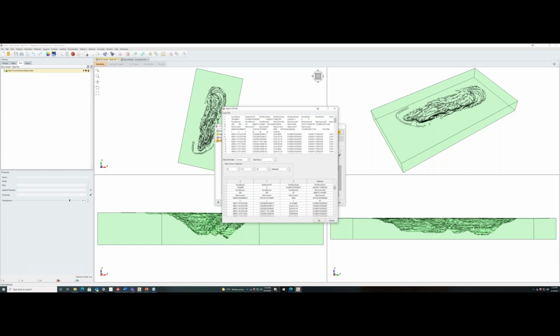When you look at the number of rows that are visible here, you see that the data starts from row 8. So I'll come here and say my data starts from row 8. On top of that, when I look at the number of columns, it's 1, 2, 3, 4, 5, 6, 7. So my material data is in column number 7. I'll change material to column number 7 and see what happens to this column here when I do that. When I change to column number 7, it lists the material types. So that's the first step we take, and then we select OK.